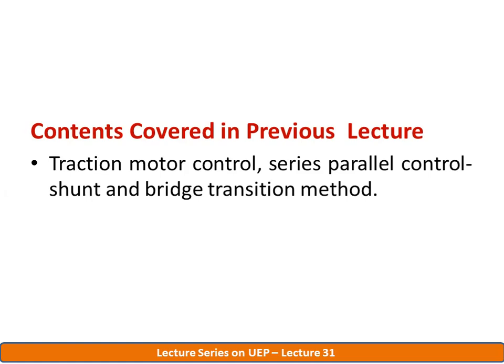Electrical supply is applied to the starter, the primary resistor. The resistance value is large during starting. Gradually, the resistance is reduced. Initially, the back EMF produced by the DC series motor is 0. When supply is applied, back EMF is 0. Gradually, the starting resistance is reduced, so the voltage drop across the starter reduces. Initially it is high. The motor gradually increases the back EMF production. As back EMF increases, mechanical output also increases.